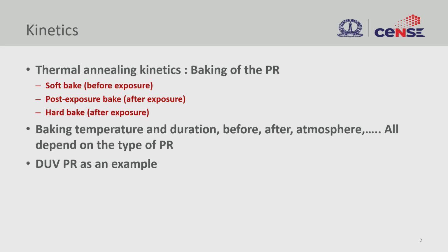This baking can happen either before exposure or after exposure. Before exposure we call it a soft bake, and after exposure we call it a post exposure bake, and sometimes you also do a hard bake, which is also after exposure.